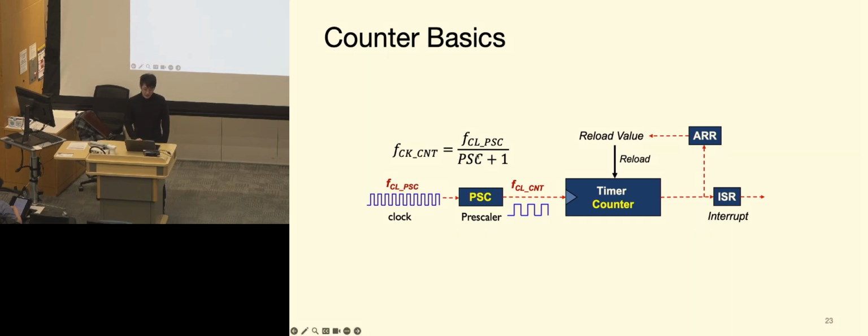So just remember that whatever number you set to the prescaler, it's technically always +1 when you're actually doing the dividing. And then it goes to the counter, which is a special register, like a time counter. This counter runs freely, and if it's enabled, it just automatically counts up, or down, or up and then down. They have different modes to choose from, and it's driven by a clock source, which in this case is the clock that comes from the prescaler.